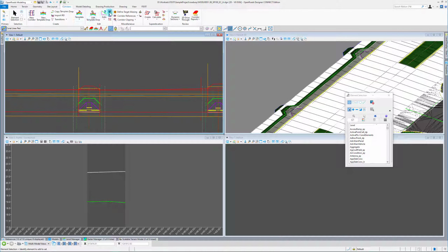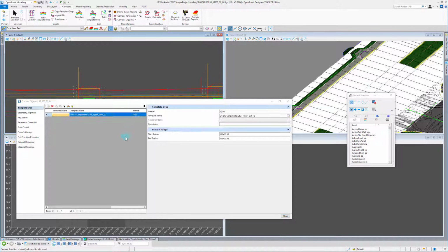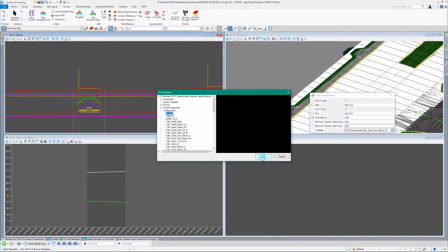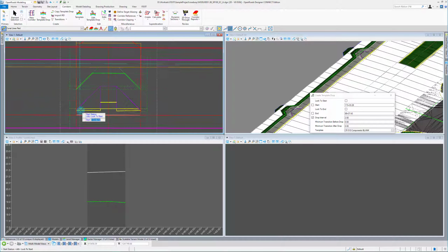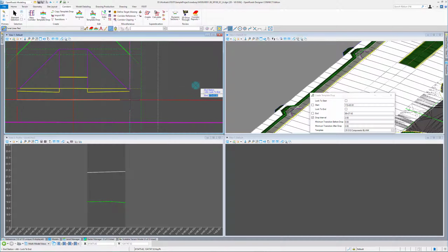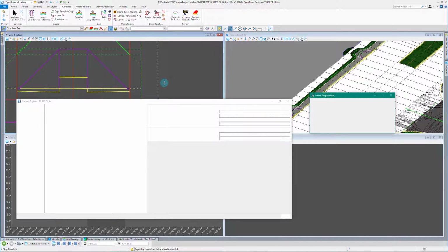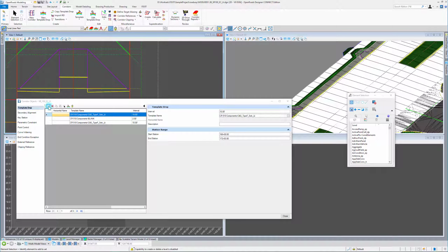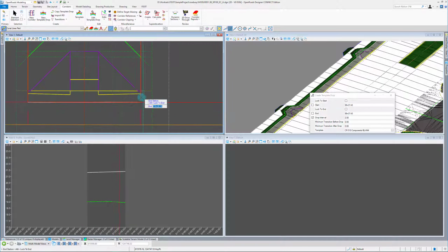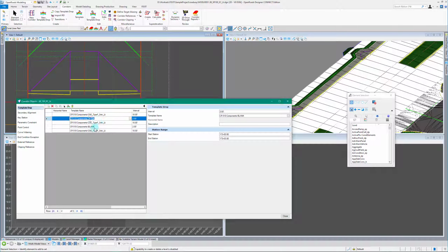So I'm going to go to my corridor, grab my bucket, get on this corridor. And remember we have our handy dandy blank profile, or corridor template drop. We're going to snap to this edge of that drop and this edge to make our hole. Choose 2. Remember, it doesn't really matter. Do the same thing over here. Make our hole. And then we can go ahead and delete those blanks.